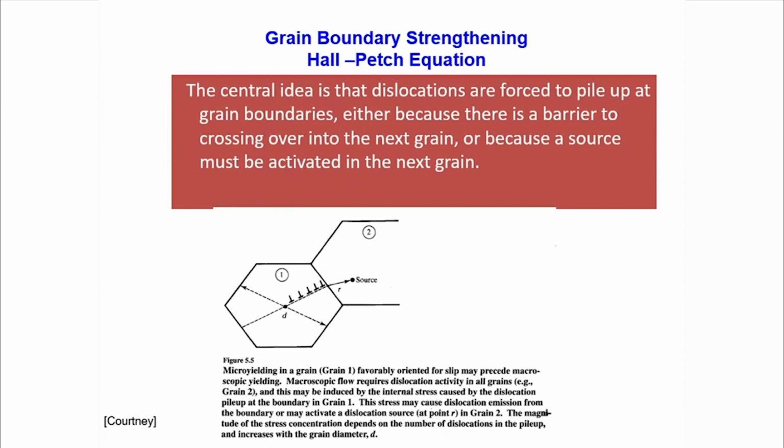So in order to start the dislocation movement process in the other grain, you need to create a source on the 110 plane. That's because it needs more stress. The critical resolved shear stress to move a dislocation on a 110 plane is much higher than on a 111 plane, because the 110 plane is not the closest packed plane in an FCC crystal. Am I clear? So these are the two important aspects which lead to the pile up of dislocations at the grain boundaries. That's something you should understand very well. And that is the main reason the grain boundaries act as a strengthening agent.